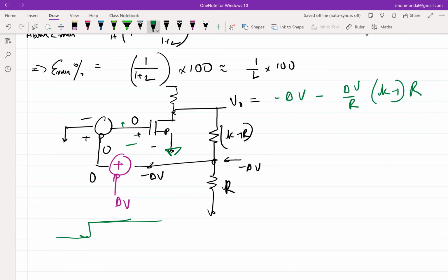If this is not 0, and if the gain is very high, then you go around the loop and see whether the loop is tending to pull that error to 0. Right? You start off by assuming the error voltage is not 0. Then you go around the loop and see whether the loop action is trying to force the error in the other direction.